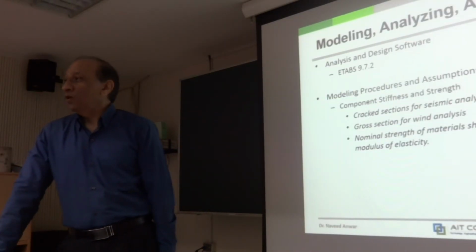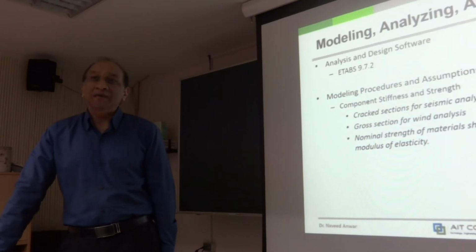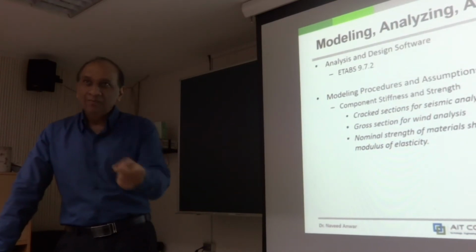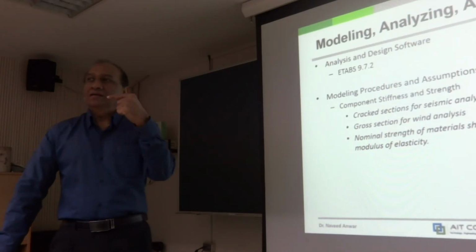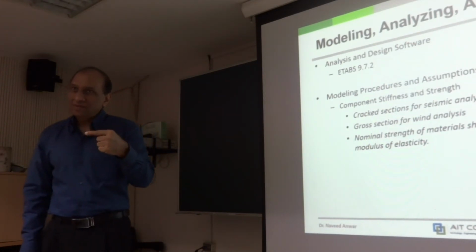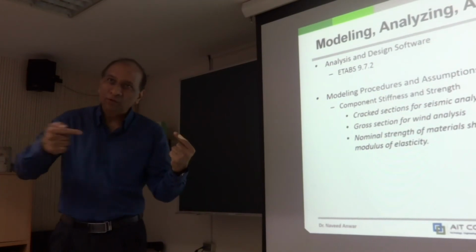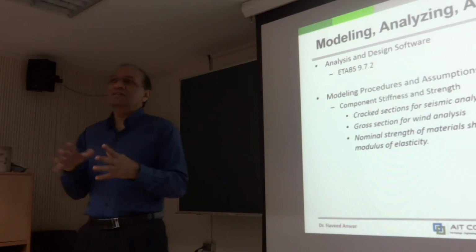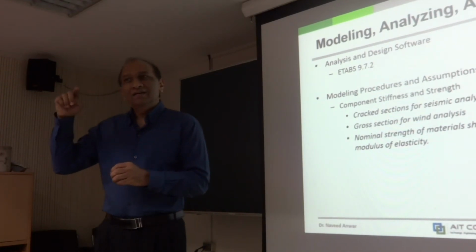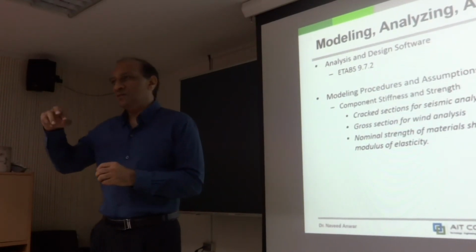Because the moment will follow the stiffness, and if the stiffness of the beam is relatively higher than columns, more moment will shift there. And similarly, if I decrease the stiffness in the beams and not in the columns, the moment will flow to the columns and reduce in the beam. Now, two situations will give me safe and unsafe results.